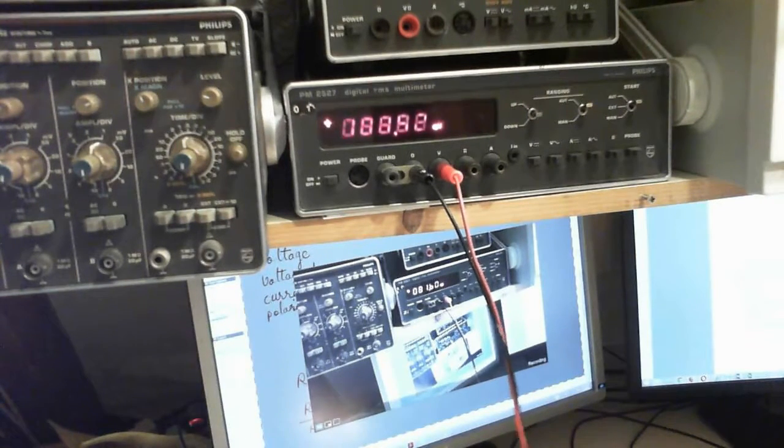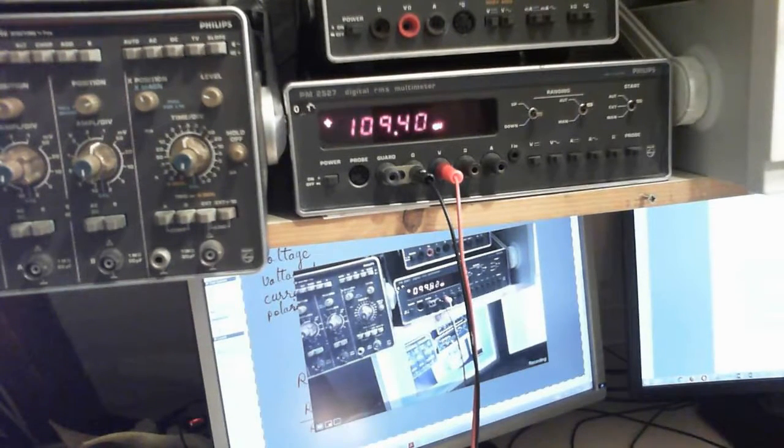Now I probe my power supply in this circuit. It's 13.4 volts, right? And so here I had basically 6.9 volts. Let me use these alligator clips. That way my job is going to be a lot easier. So I go to one of the lamps, and that is 6.9 approximately. Now I'll go to the other lamp. And probe the other lamp. And now I'm getting 6.4 volts.